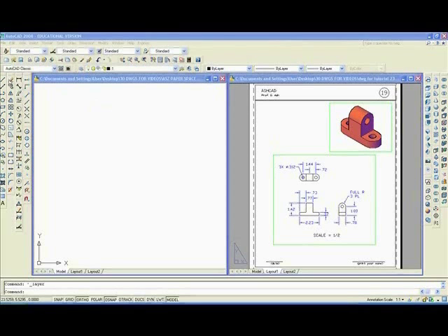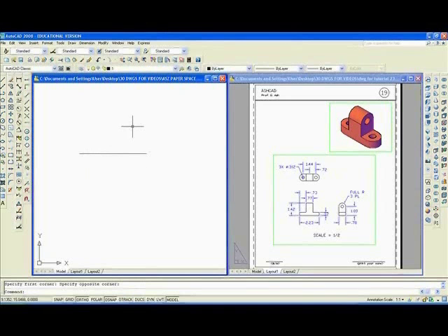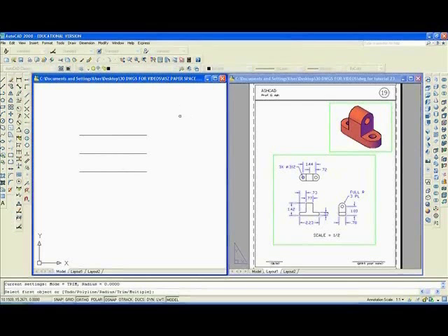Let's start exercise 19 by drawing a horizontal line. We'll make that line 1.44, enter. Of course, to see it we'll have to zoom it up. Now we're going to take half of 0.78, which is 0.39. Offset, O enter, 0.39, and offset on either side. And it is a quirk of AutoCAD that if you want to put a fillet